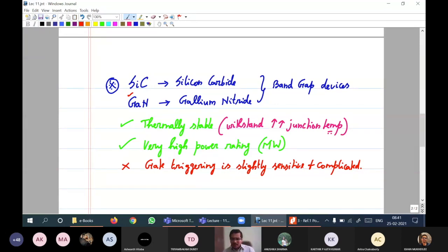I'm not getting into the structure of SiC, the operating principle and other things, because again, it is beyond the scope of the syllabus. But anyway, you should know these things. That is why I'm saying these things. Not outdated things like what is the on-state voltage drop of a diode, and you will write 0.7. If it is correct, I will put 1 mark. No, that is wrong. Wrong meaning practically, it is not 0.7 always.